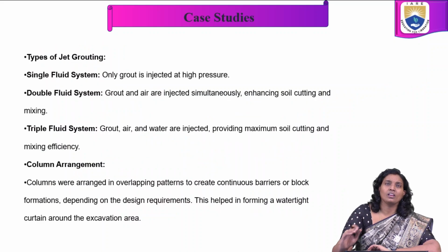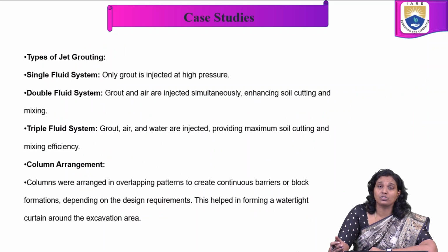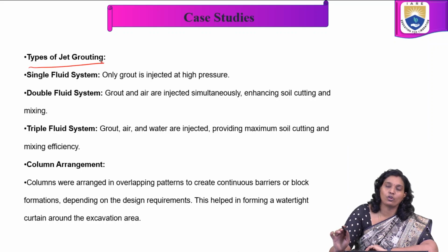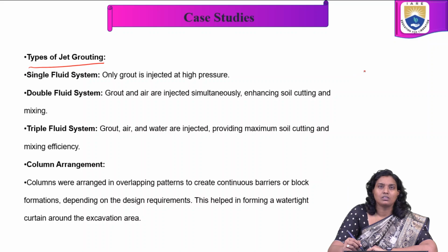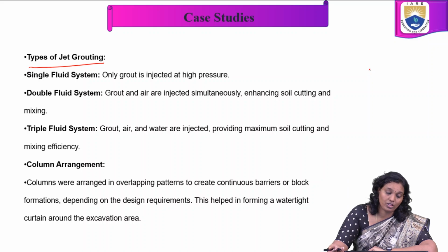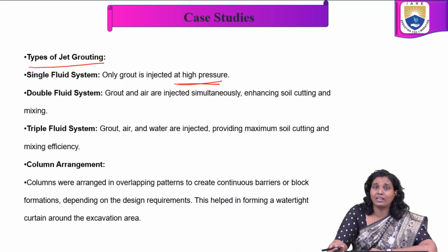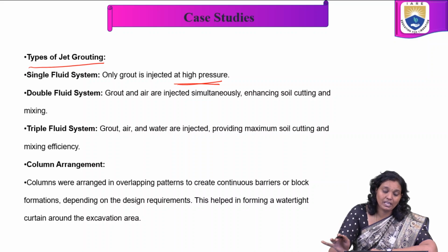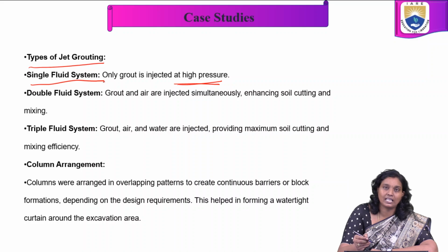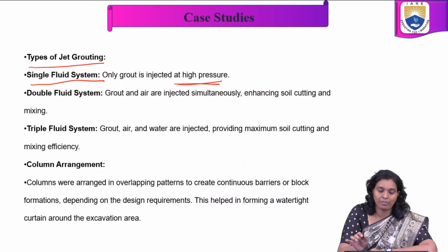Now, different types of grouts, we already talked about this. It depends upon the requirement of the project. The type of jet we choose depends upon what kind of soil it is and what kind of requirement it is. In the single fluid system, only grout is injected at high pressure. As per the project requirement, if it requires only high pressure, we use the single fluid system, where only grout is injected at high pressure.